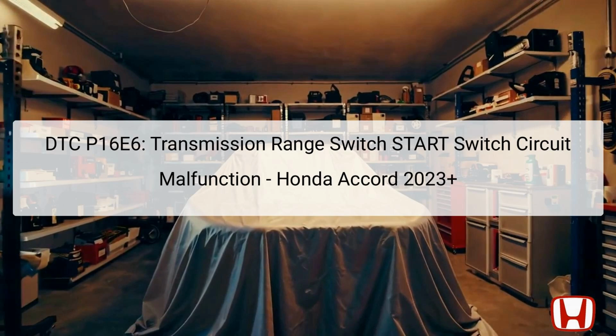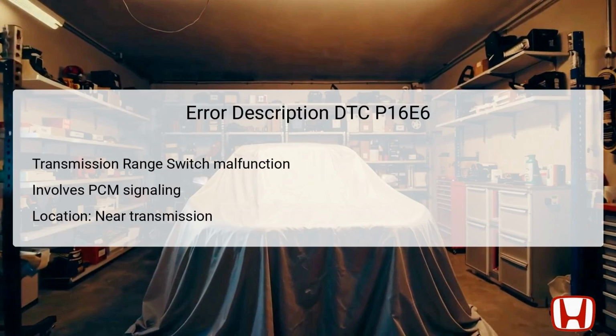When an irregularity in the signals occurs, such as when you shift out of the expected P or N position, the PCM detects it as an anomaly, resulting in the storage of this diagnostic trouble code, DTC. Identifying and repairing this issue is essential to restore optimal vehicle performance and ensure safety during operation. The DTC P16E6 pertains to the transmission range switch, which is essential for proper transmission functionality.